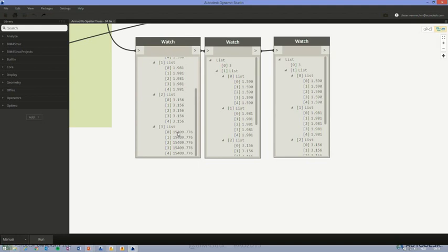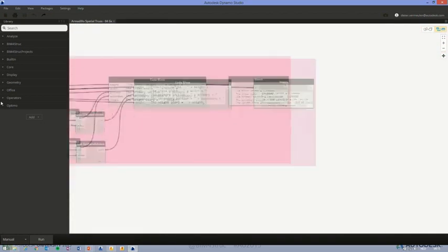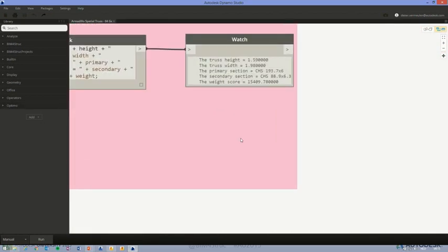So it's not me deciding to find a value between 1.5 and 3 every 10 centimeter, for instance. No, it could be something like every 1 centimeter or even every half centimeter, right? That's what the genetic algorithm is doing. It's deciding itself which value to take and then brings that back into the results population. So meanwhile, it's almost finished. We have 11 models already.